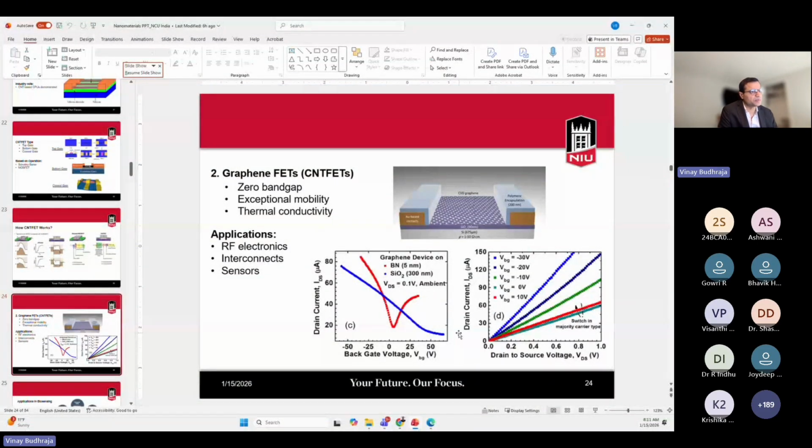In the graph, you can see how the drain current varies with respect to the drain to source voltage. Because the device sizes are so small, the device turns on very fast, so that's why saturation sometimes is missing in the graphene based FET. But it has its own advantage, that it has very high on to off ratio, and that's being reflected in subthreshold slope.